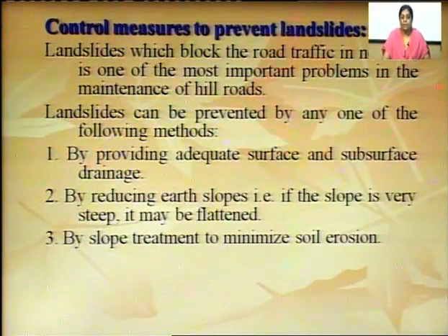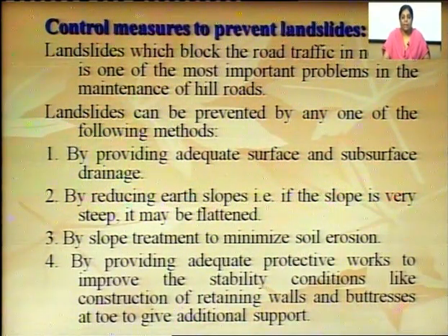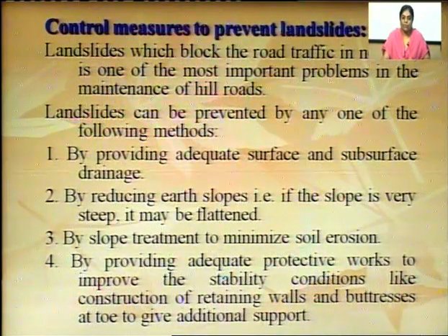by slope treatment to minimize soil erosion by mulching and other treatments, by providing adequate protective works to improve the stability conditions like construction of retaining walls and buttresses at toe to give additional support.